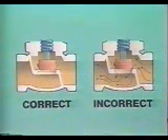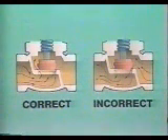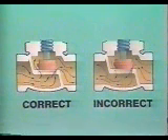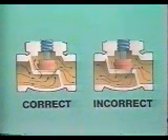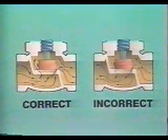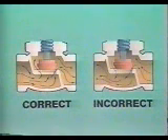A globe valve is usually set up for throttling so that the flow is from below the plug, which tends to open the valve. This provides a more stable operation and eliminates slamming or closing as the plug nears the seat ring. Flow from the other direction would put pressure on the top side of the plug and could close it.